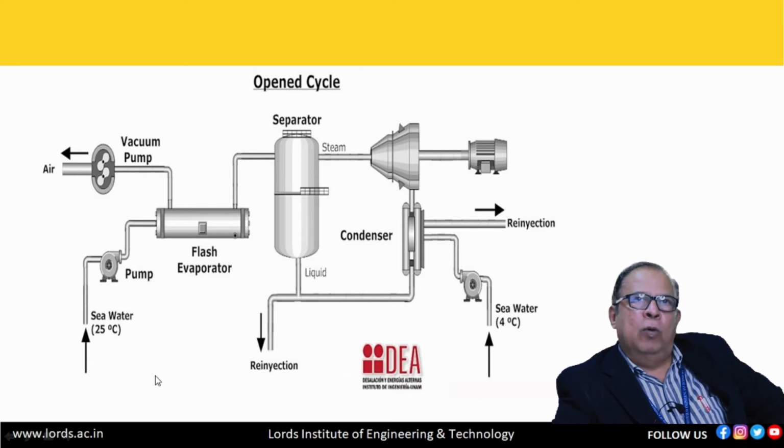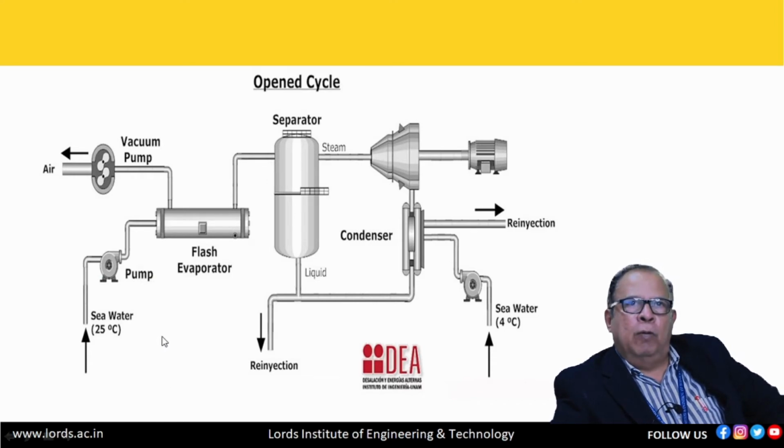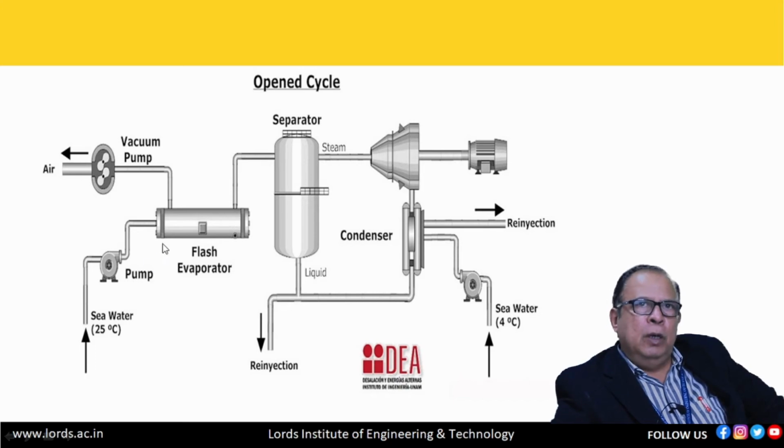Then we will study the open cycle OTEC power plant. Here we are not using any refrigerant. We are not using ammonia. Here the cycle is open. You see here the seawater, which is at 25 degrees, is flashed in the evaporator. That means we are maintaining some vacuum in the evaporator. So when we maintain some vacuum in the evaporator, what happens? Here we are using a pump to maintain the vacuum.